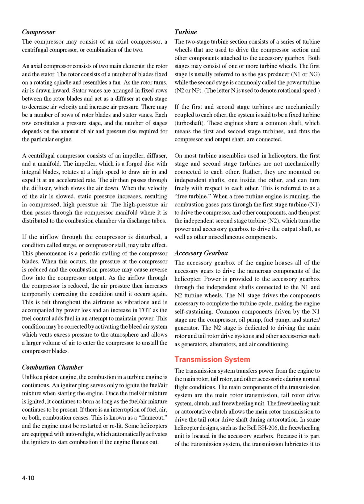This condition may be corrected by activating the bleed air system, which vents excess pressure to the atmosphere and allows a larger volume of air to enter the compressor to unstall the compressor blades.